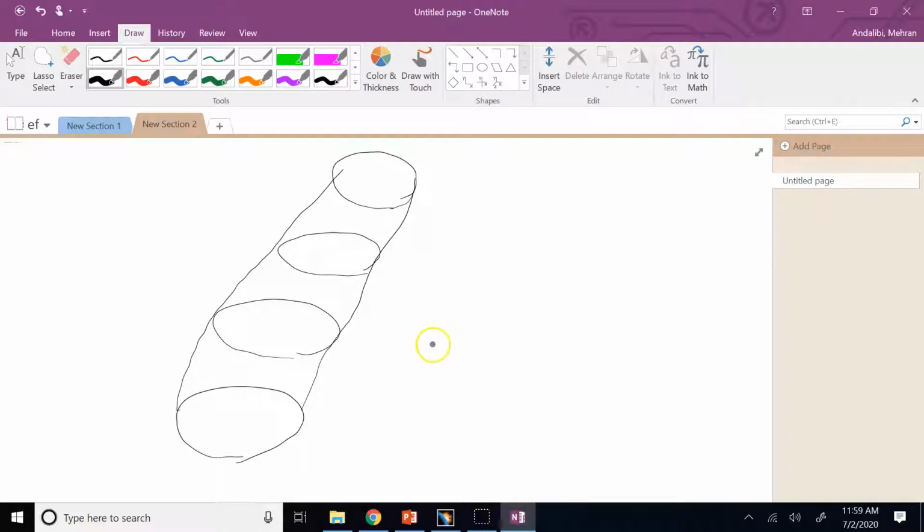Also, the wing of an airplane, as I told you, there is this airfoil where it attaches to the body, and then the tip. So this is the root, the part of the wing that is attached to the fuselage, but the tip of it, which is exposed to the air, is not typically the same size and the same shape as the root. It's a different shape and a different size. And when you connect these two together to create the wing, you need the multi-section.